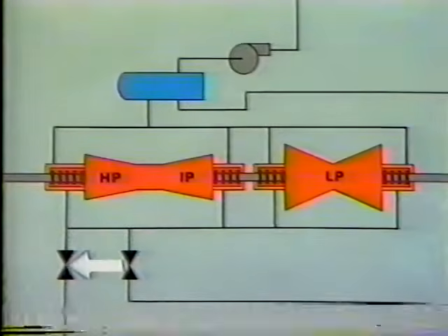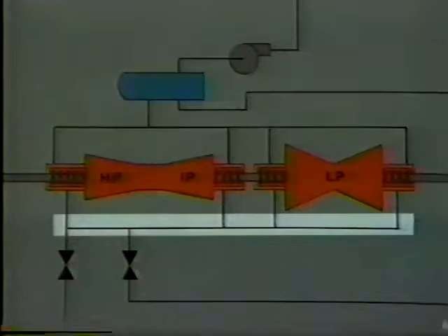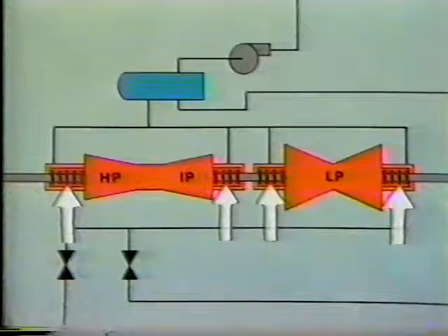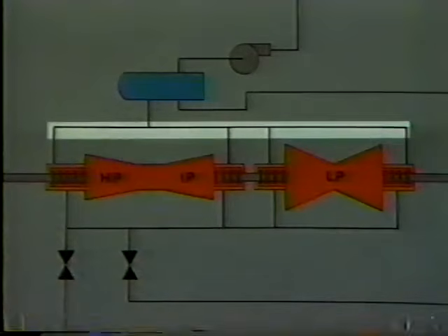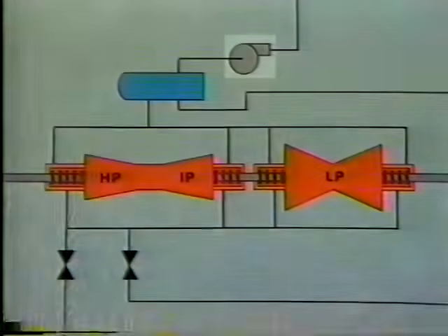There's a steam supply control valve, a steam unloading control valve, a gland seal supply header, glands, a gland seal exhaust header, a gland steam condenser, and finally, a gland steam exhauster.